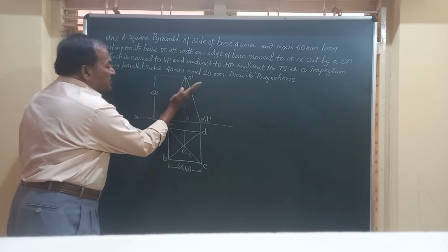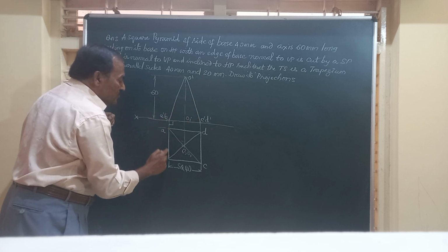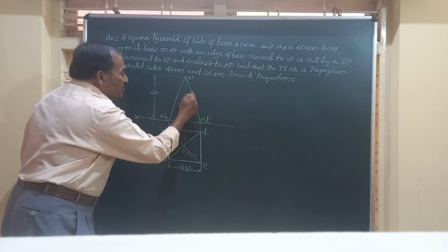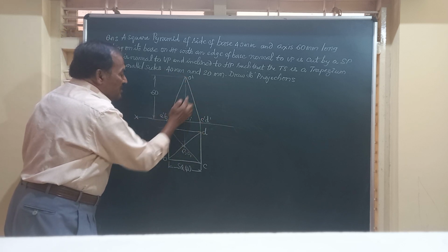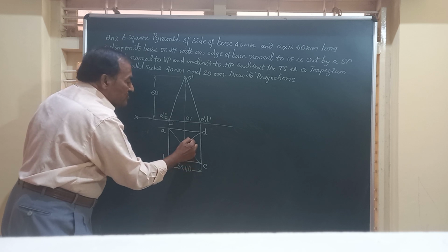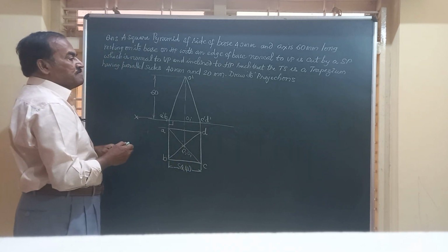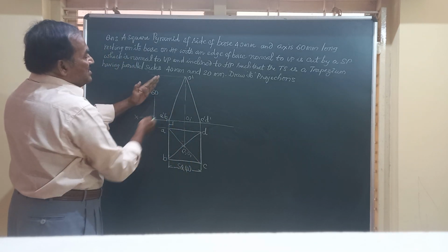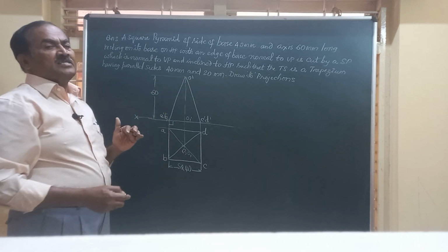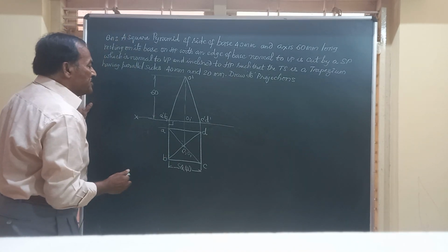That is, the section plane which is normal to VP and inclined to HP passes through AB, which will give the dimension 40 mm, and somewhere on OC and OD you will have 2 more points and the distance between them is necessarily 20. This is 20, this is 30. And when you cut this solid and throw away the upper piece, you will see in the true shape a trapezium. So friends, what can we do here?